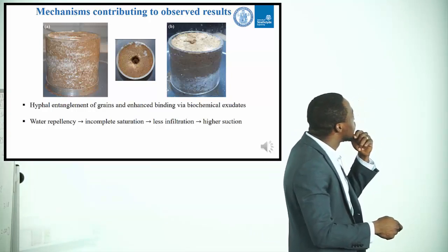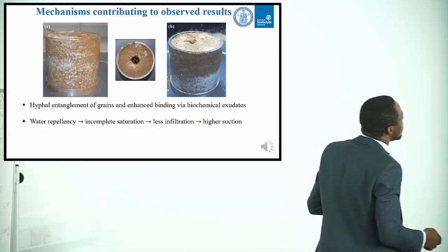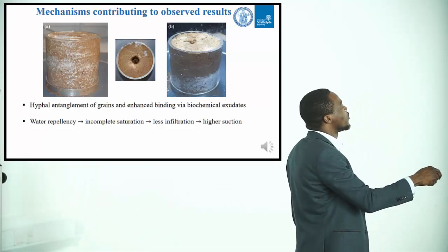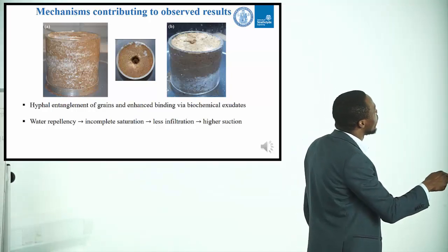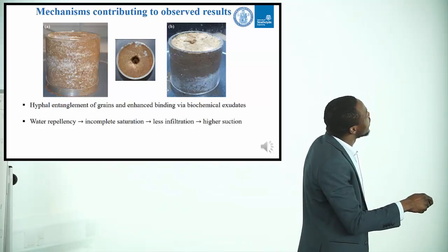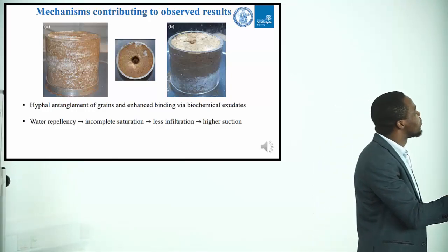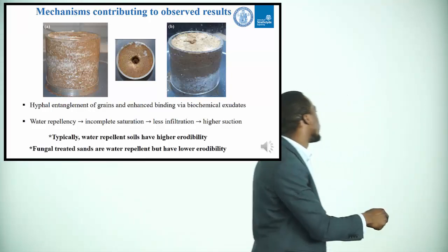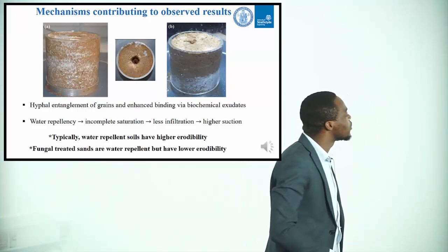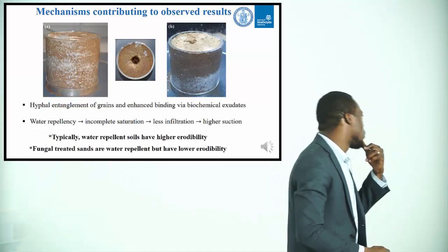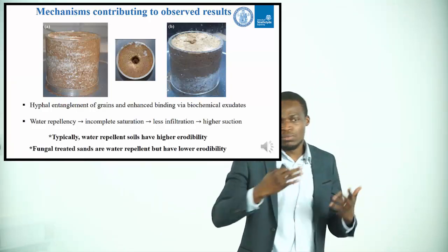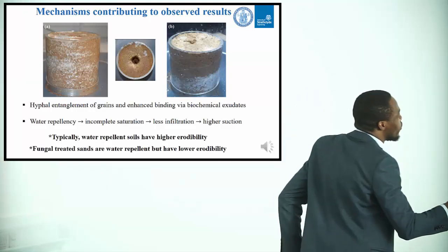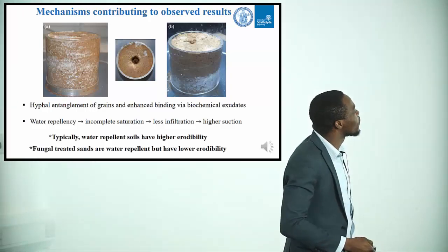And if we place all of this together on the erodibility chart, again, we see that the very erodible band is shared between the untreated specimen and most of the 1 week surface treated specimens, and some of the 1 week fully treated specimens. We see all the 1 week treated specimens falling into that band, and most of the others are just here where you can't really pick out significant difference between the growth at that point. So meaning basically that after 3 weeks of treatment, we see no significant difference in the erodibility effects that the fungal growth has in the soil.